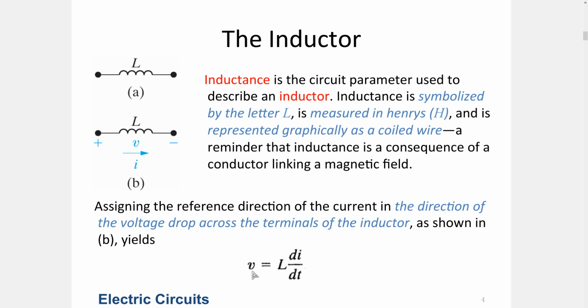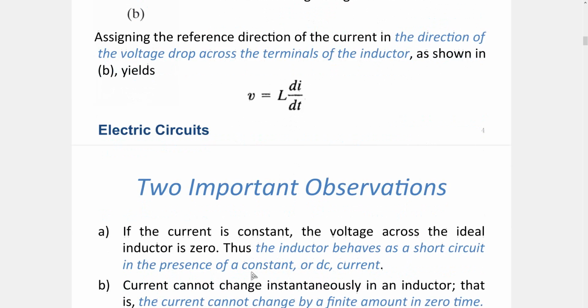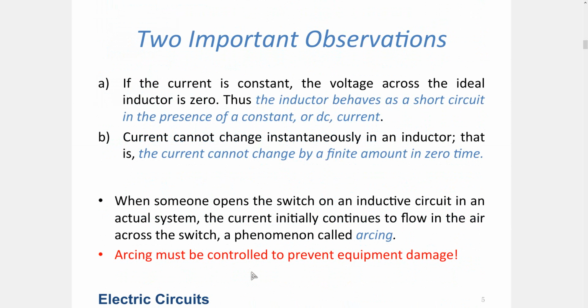So in practical life, there are many interesting applications of this, but in regular circuit design, we have to make sure that the voltage across this inductor is controlled, because if you indefinitely let the voltage increase, then other components connected, especially the semiconductors, are very sensitive to high voltages, and they can get damaged. Okay, so sometimes you can also encounter this event when you are turning on and off some circuit that contains an inductor.